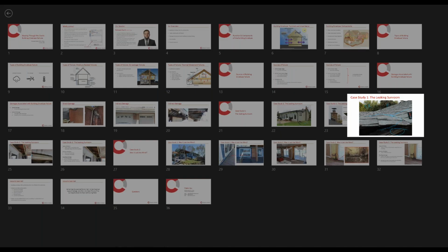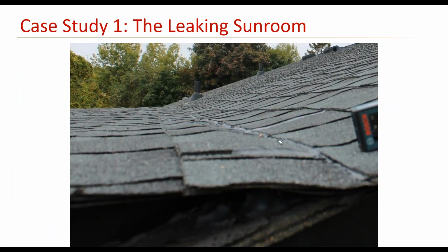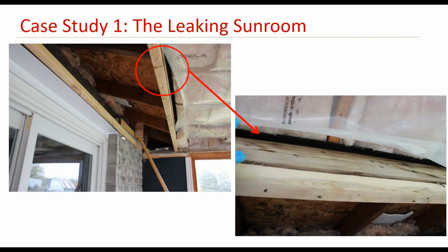The restoration contractor here, in a trial to just remedy the situation temporarily, applied some sealant at this location so that water cannot get back into the sunroom space.